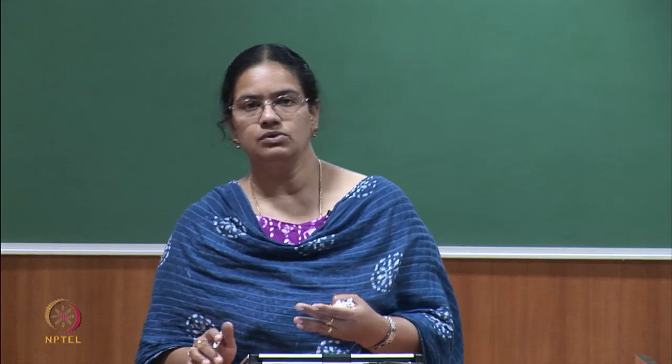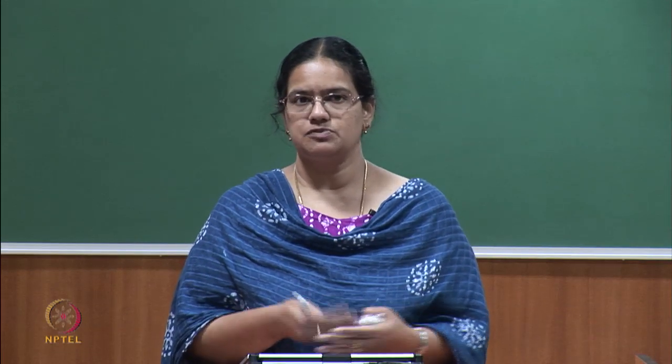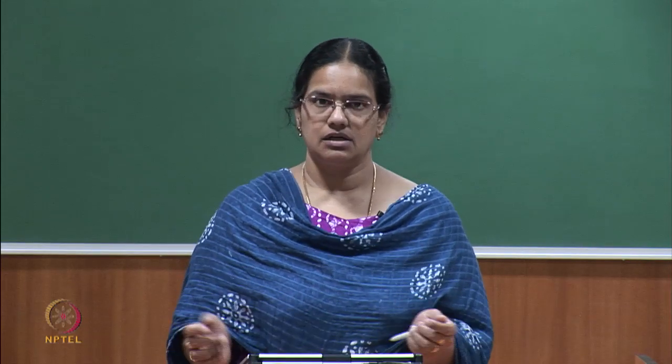I also explained how to define the logic. I also cautioned you about the issues that may come up when you are putting in the relationships. When you are putting in the relationships, see to it that you do not end up with something called neutral critical or reverse critical. So, be careful in how you represent the relationships, and then you should be able to build a proper network. Okay. As far as software is concerned, CPM or PDM, MS Project, Primavera, any software can handle all 4 relationships along with the lead or lag constraints.